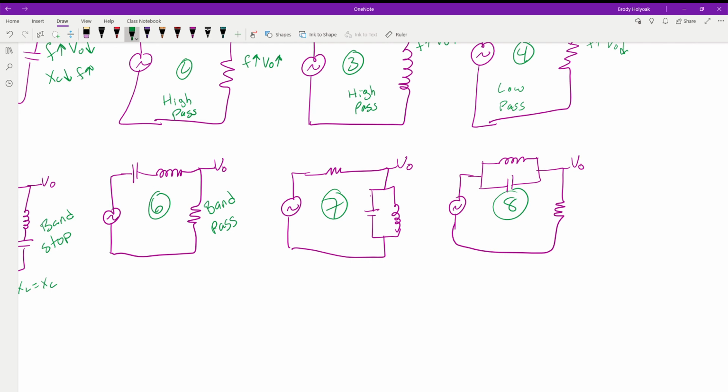So then if we have a low resistance compared to a higher resistance, or compared to what it was at resonance, the voltage out is going to go down. So with our reactive components in parallel against the resistor, with the output taken across them, this is going to give us a band pass, because this is the highest voltage that it's going to get, and then at the up and down frequencies, this is going to get lower and lower.